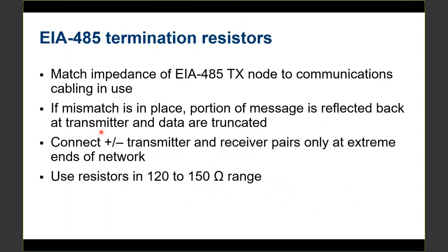Okay. And then as far as termination resistors go, I really don't like talking about termination resistors too much, because nowadays a lot of relays and devices end up having termination resistors sometimes built into the devices. So they're less and less commonly used. If you have a 485 network set up and everything is communicating properly, then you probably don't need a termination resistor.